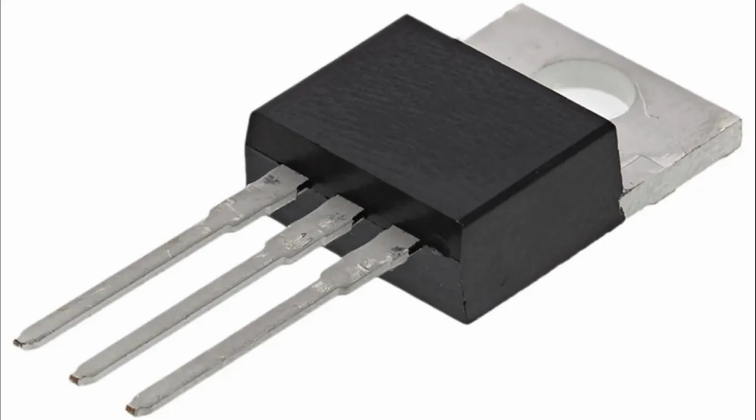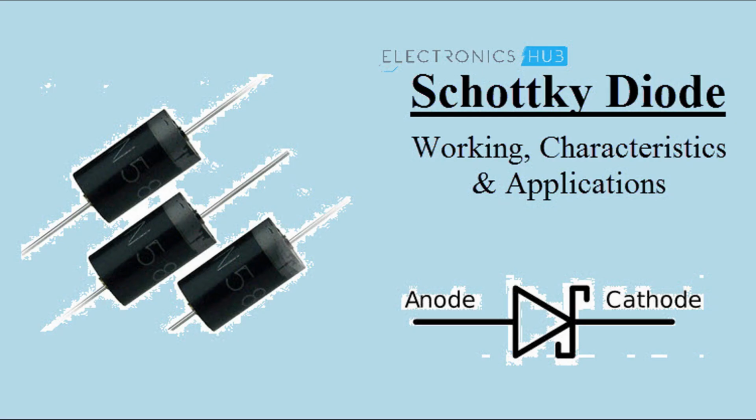Some materials, like metals, typically have a positive temperature coefficient of resistance, PTC, meaning their resistance increases with temperature. On the other hand, some semiconductors have a negative temperature coefficient of resistance, NTC, meaning their resistance decreases as temperature rises. Semiconductor properties. The performance of semiconductor devices, such as diodes, transistors, and integrated circuits, can be affected by temperature variations. Temperature sensitivity can influence parameters like forward voltage drop, leakage currents, and switching characteristics.